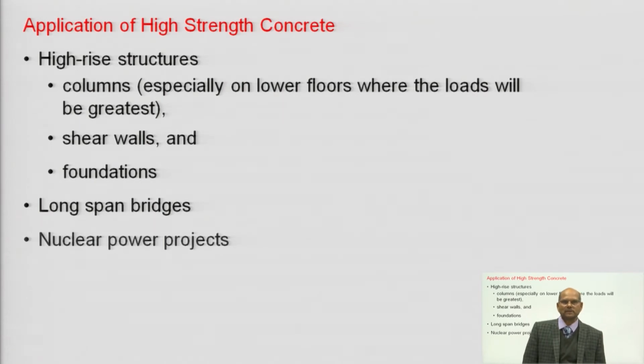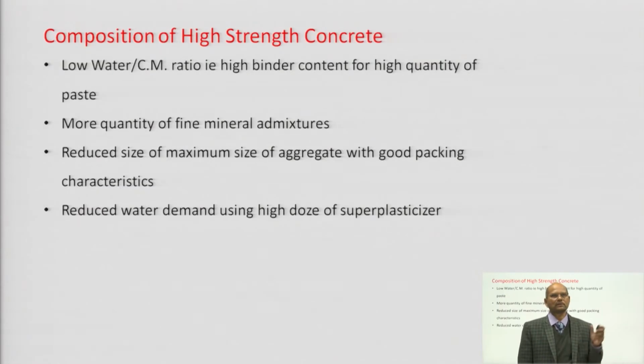Similarly, we have long span bridges, where the dead load is more, so in that case we can consider high strength concrete. Even for nuclear power projects, suppose you want to make a dome, that dome can be done with pre-stressed concrete, and there you can use high strength concrete. So these are the important applications of high strength concrete.